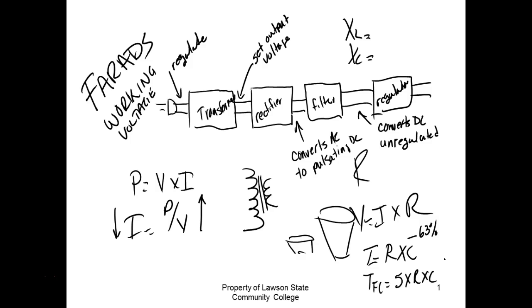And then we transpose this formula to actually calculate our ripple voltage. We transpose this formula right here also to figure out what size capacitor I want. So this is the makeup of what we call a linear power supply.